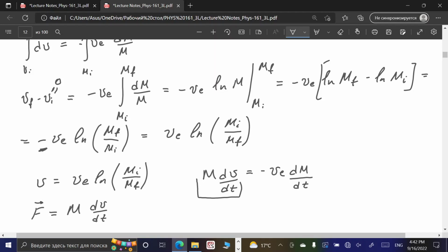And what is nice about this propulsion motion, since we have a system with changing mass over time, we can represent it as follows from this equation: as the absolute value of the exhaust velocity times the first derivative of the mass of the rocket over time. So again, looking at this equation, we see that the propulsion force which is supposed to accelerate our rocket, which we want to be as high as possible, will be linearly proportional to the exhaust velocity. We already mentioned that it is an important parameter in both equations. So we want to increase the temperature of burning inside the rocket engine.